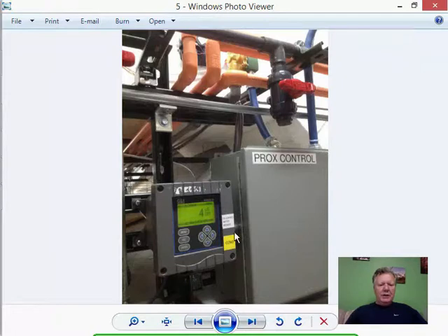This is the controller that actually opens up this solenoid right here to let a very small amount of water in every time it drops to 3 microsiemens. Right now we're at 4. When it drops to 3 microsiemens, that's when the solenoid opens up and it's throttled to add the water slowly, and only about a cup, 8 ounces, half a cup, gets added each time to the 20-gallon tank that's up there.